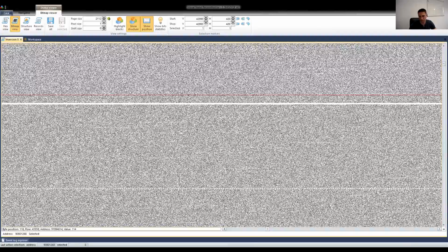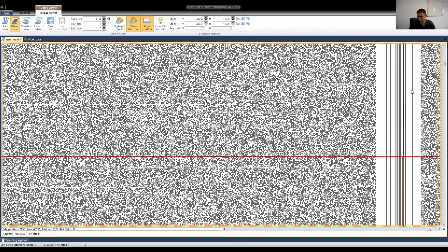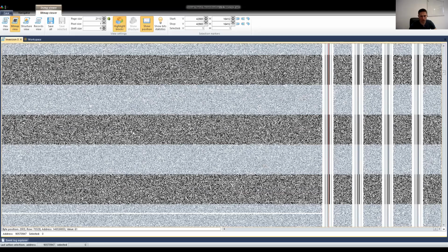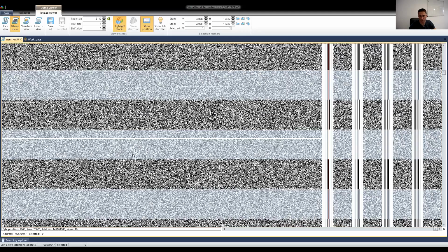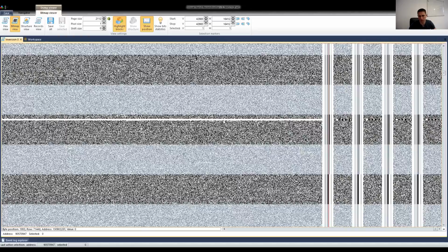Go to scroll it to some data area. Okay, it's here. As you can see, blocks are quite small here. Let's search for some clear patterns. Actually, this line is the pattern also, and you can see that all blocks have just one line, one line, one line. In case of multiplane page allocation, I would see a second line somewhere here, but I see just one line. The same as here.